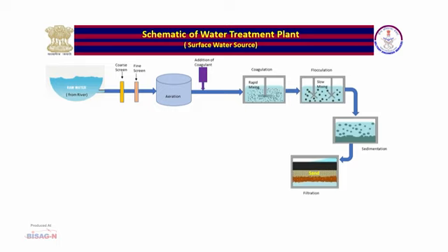Depending upon the point at which chlorine is added, it can be either pre-chlorination, where chlorine is applied to water prior to any unit treatment process, and post-chlorination, where chlorine is applied to water before it enters the distribution system to maintain the required amount of free chlorine. Complete data are unavailable upon which to base recommendation of residual chlorine requirement to ensure destruction of waterborne diseases. However, in practice, 0.5 milligram per liter of free chlorine for 1 hour is sufficient to inactivate virus even in water that was originally polluted, and hence this may be adopted to make the water safe.